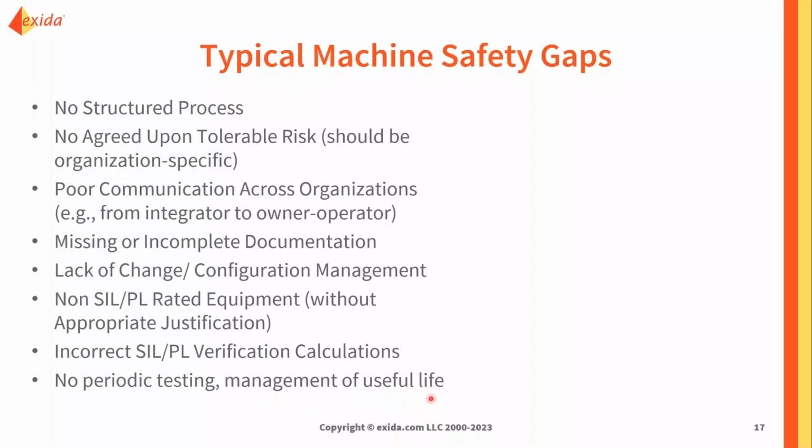Also thinking about the useful life for components, where a lot of machinery standards assume a 20-year life of the machine, but that may not be the useful life for that individual component. And in particular, we see a lot of times with hydraulic systems or pneumatic systems that a solenoid valve may only have a useful life for certain components of 3 years. And if we're relying on that to act for a safety function, we install it and are going to run it for 20 years, that safety function may have components that aren't going to work anymore.